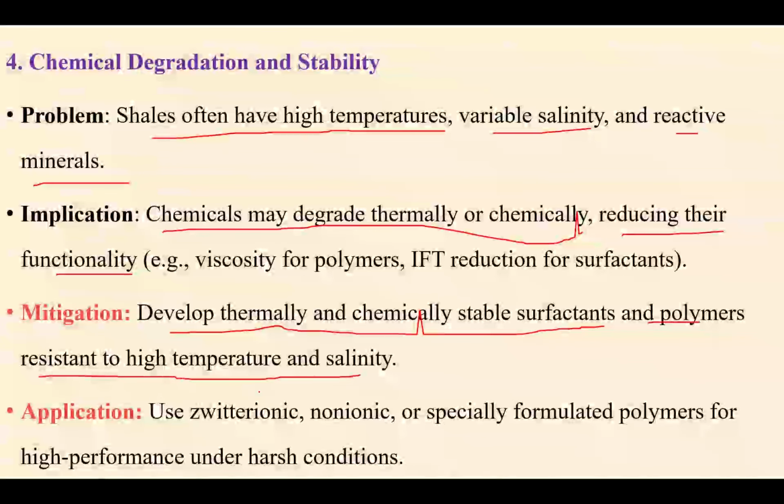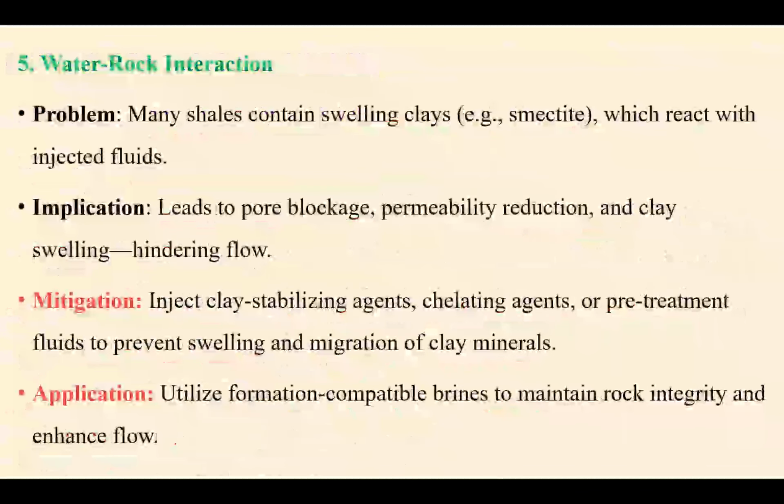So here, use different zwitterionic surfactants or non-ionic surfactants, specially formulated. You have to go for tailor-made surfactants or polymers that show performance under the harsh conditions of the reservoir, that is, the high temperature and high saline condition.